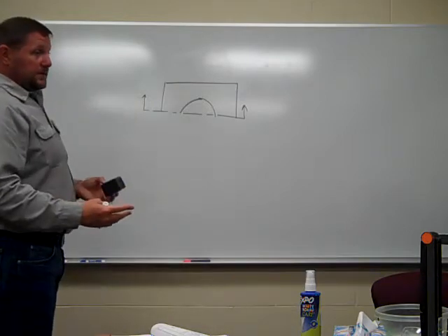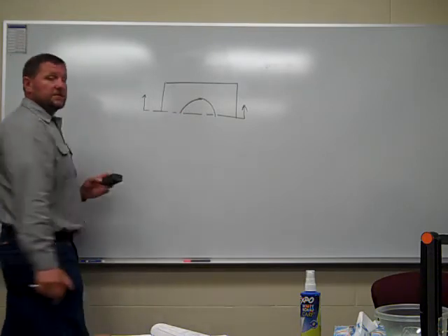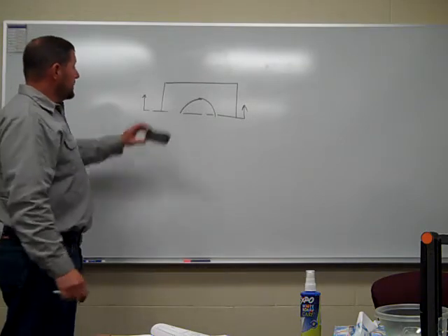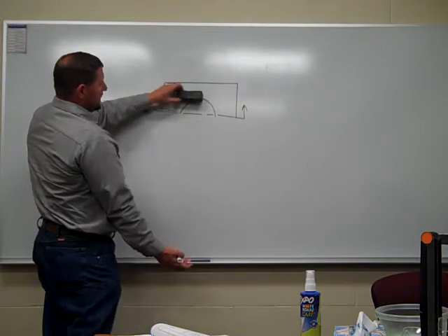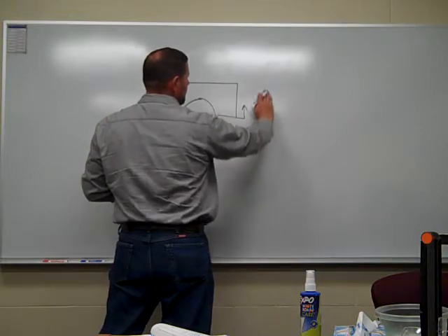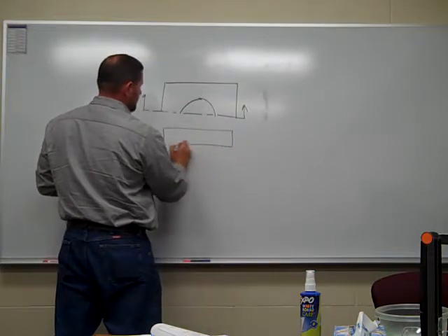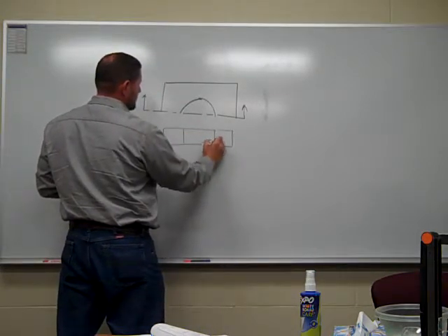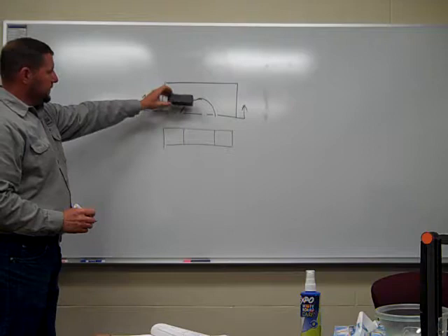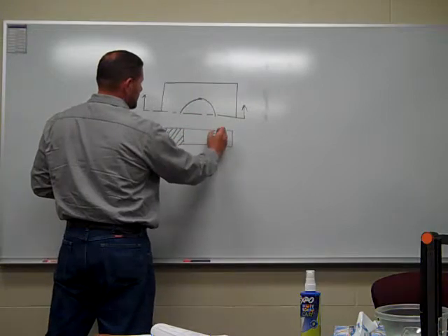Cutting plane lines are basically telling you there's a section view. Section views are used to show internal features that we can't get on the print, or we need more clarification in a certain area of the print. So basically we cut the whole bottom half off and we're rotating it. For example, that would look like this. I'm going to draw it underneath so you can see a little better. Here's our plate. Here's our circle. We took it like this, turned it sideways, flipped it, so that the arrows are telling us what direction to look. This goes into our next line, section lines.